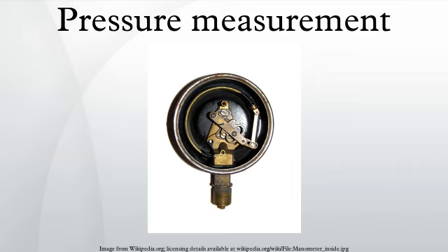Cold cathode. There are 2 subtypes of cold cathode ionization gauges, the Penning gauge, and the inverted magnetron, also called a redhead gauge. The major difference between the two is the position of the anode with respect to the cathode. Neither has a filament, and each may require a DC potential of about 4 kV for operation. Inverted magnetrons can measure down to 1x10^-12 torr.